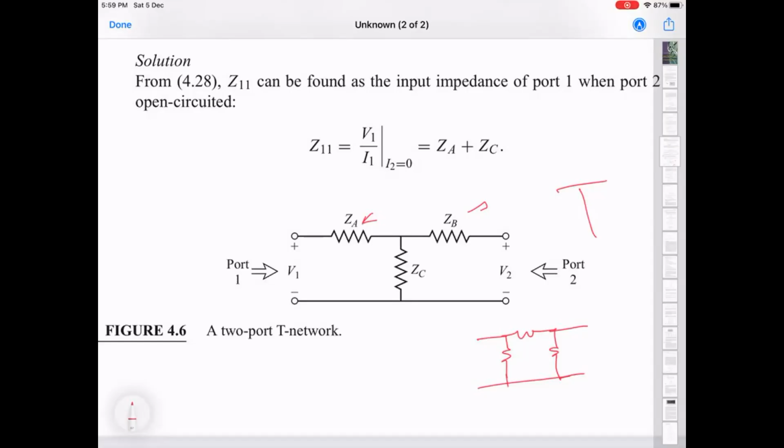like this, so that you can see, because in this network now you are seeing the different impedances. ZA is an impedance, ZB is an impedance, and ZC is an impedance, but the elements of the matrix are not a direct connection to a physical impedance. So this connection becomes a lot more apparent here. To compute Z11, we have to compute the ratio V1 over I1 with all the other currents at 0.